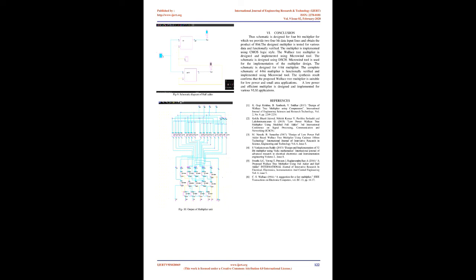Microwind supports the entire front-end to back-end design flow. We have DSCH, the Digital Schematic Editor, which possesses an inbuilt pattern-based simulator for front-end designing. The user can also build analog circuits, convert them into SPICE files and use third-party simulators like WinSPICE or PSPICE. DSCH can convert digital circuits into a Verilog file which can be further synthesized for FPGA/CPLD devices of any vendor. In Microwind, the same Verilog file can be compiled for layout conversion.